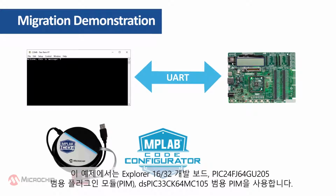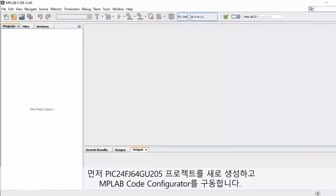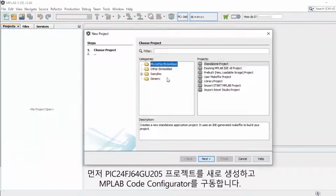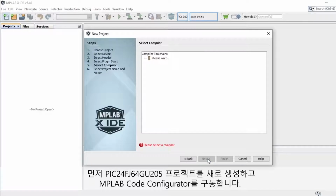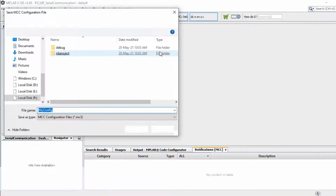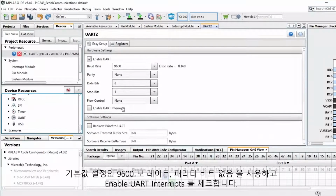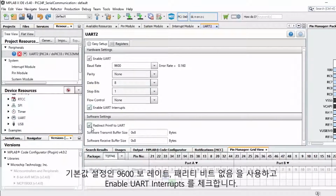To run this example, we'll be using the Explorer 16/32 development board, a PIC24FJ64GU205 general-purpose plug-in module, and the dsPIC33CK64MC105 general-purpose PIM. First, let's create a new project for the PIC24FJ64GU205 device and launch MPLAB Code Configurator. Add the UART from the Device Resources viewer. We'll use the default configuration of 9600 baud rate, no parity bits, and enable the UART interrupts.